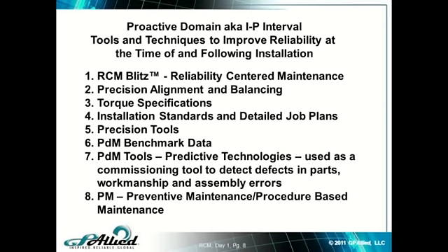I can't tell you how many plant sites I go to, and as I'm performing an RCM analysis, I begin talking about gasket or seal failures due to improper torque, and I ask, do you have a torque wrench? And somebody will say, well, we have one in the maintenance shop. And how many people work in that shop? Well, we've got 27. So one torque wrench for 27 people. How many things do you think are being torqued? Same thing goes with the companies that are installing the assets for you if you're not doing it yourselves. I find the same thing. We have to have those things in place, the standards in place, and we need to make sure they're done at the time of installation.